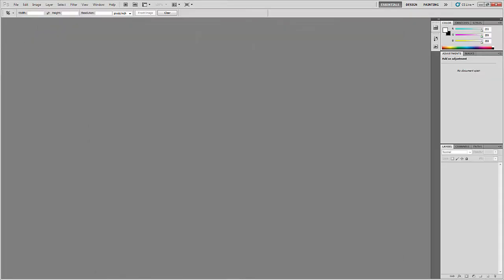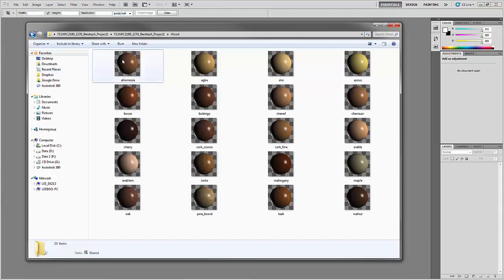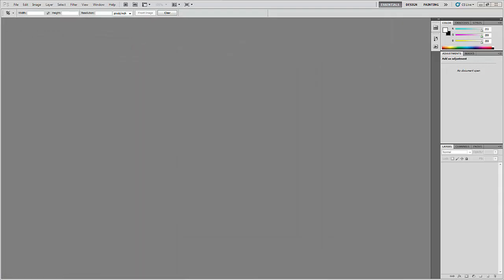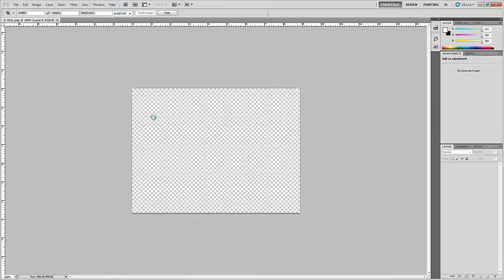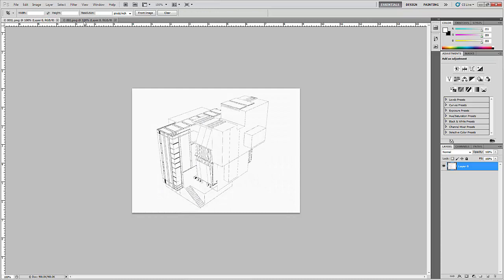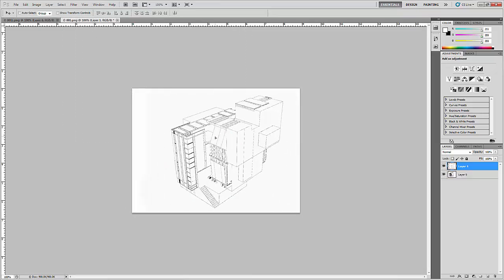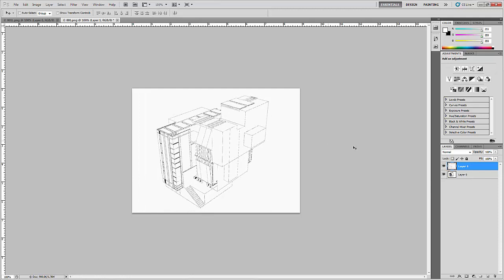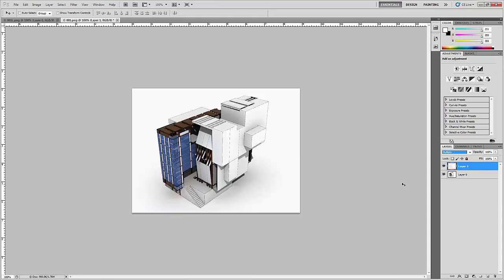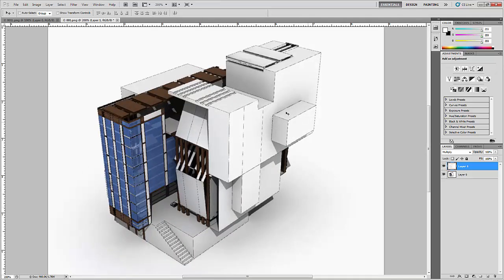in, let's see, both of those in Photoshop. Okay, one here, right? So Control A to select all, V to move it over here, overlay it. It'll snap into place, and it should be in the right location, right? And then with the top line layer selected, you can select multiply. And with multiply, that overlays the line weights into the right location.